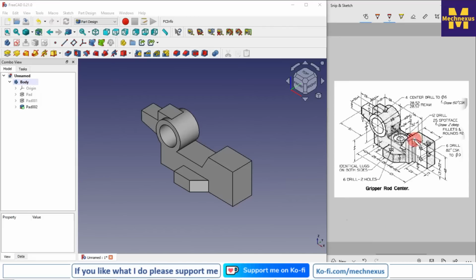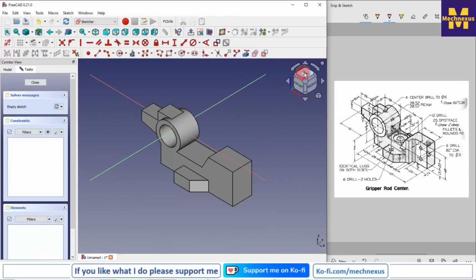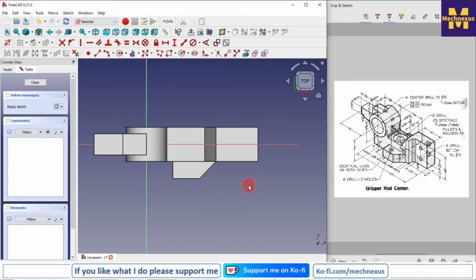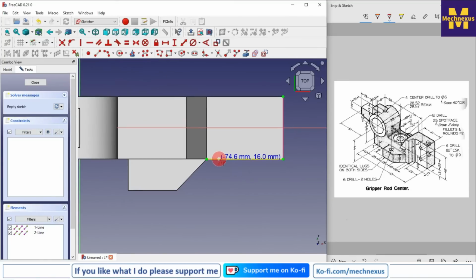Our next feature will be this pocket. We will create this cut here. So for this we will select this top plane and create a sketch, and switch to the isometric. Now we will project our geometry. We require this geometry and this one. Now we will select the polyline tool and we will create a rough profile.